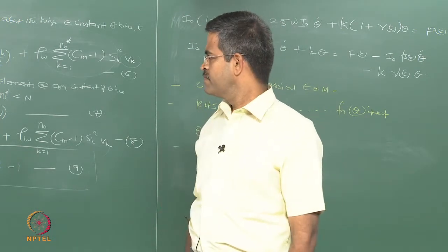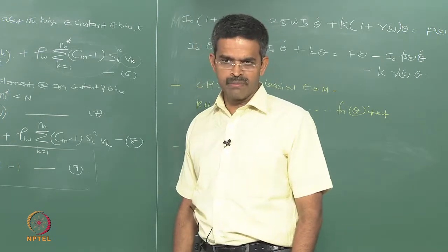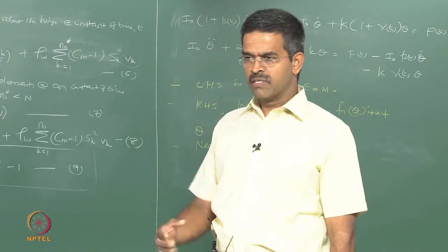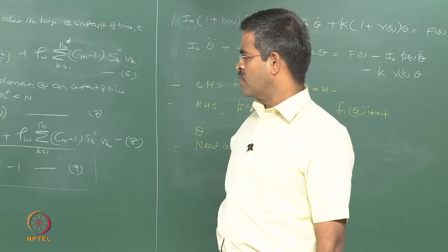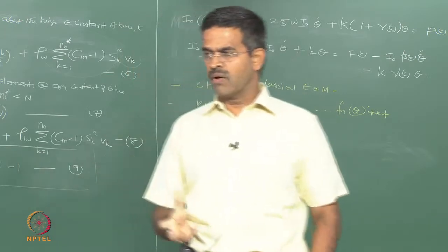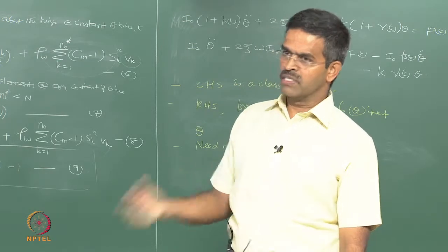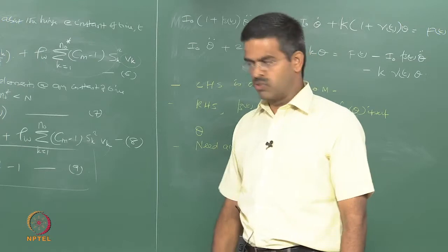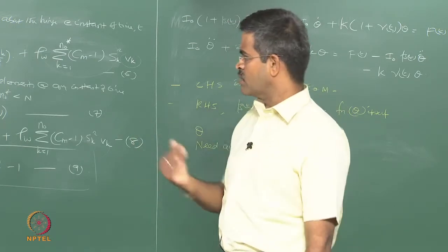Please recollect that the wind velocity spectrum also has a nonlinear term as given by the Emil Simiu spectrum, which we had discussed in the earlier module. So, there are two nonlinearities coming into play here, because one is called the static component and the other the gust component. So, there is a nonlinearity term there also, which we say the aerodynamic admittance function can convert into an equivalent static term, which generally the design people use in the design offices. So, there are two nonlinearities, one comes from the wind load, one comes from the wave load.